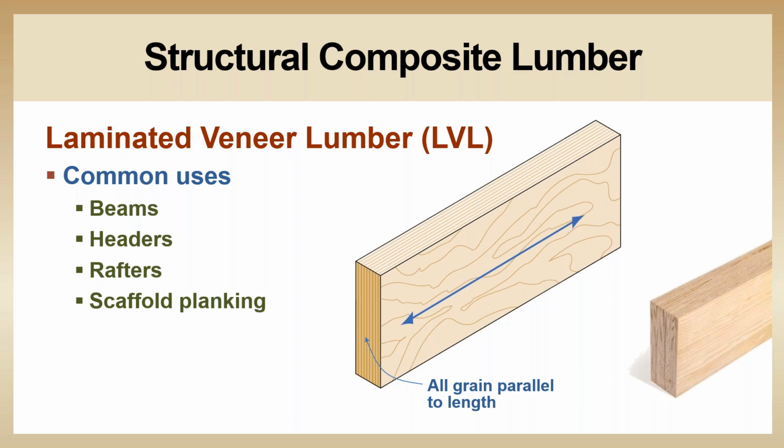Laminated veneer lumber, or LVL, beams are commonly made in depths which match the depths of I-joists. Deeper LVL dimensions are also available. The most common thickness is 1.75 inches, but LVL is available in thicknesses up to 7 inches. And they're commonly available in 1.5E, 1.8E, and 2.0E in bending stiffness or modulus of elasticity. The modulus of elasticity measures the object's ability to resist being deformed. So the higher the modulus of elasticity, the better to resist deflection.